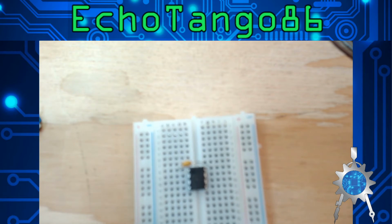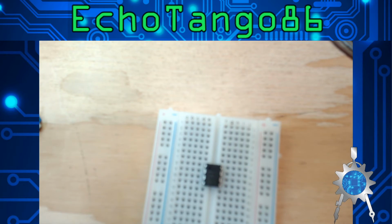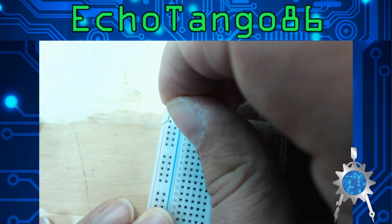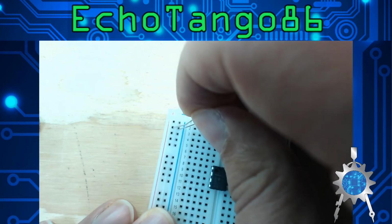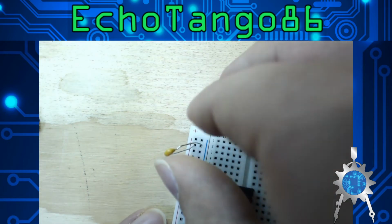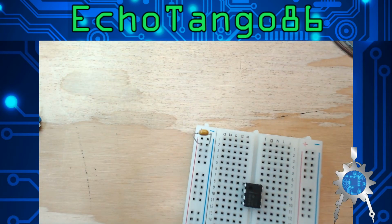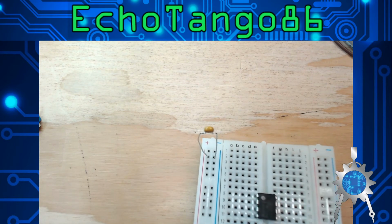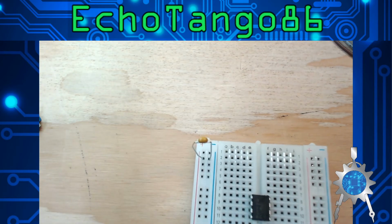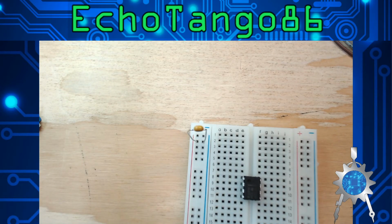And essentially what you're trying to do is smooth out the supply voltage coming through. So here's a little trick in this case. Just put your capacitor and have it go right between positive and negative. Like that. There you go. Right there. And what that'll do is it'll smooth out any voltage inputs that you have, which is nice.